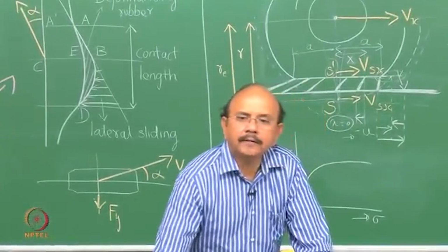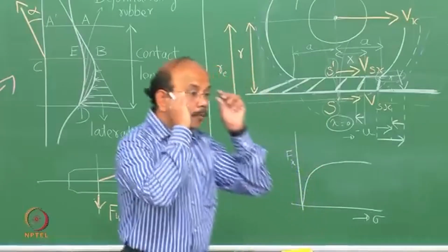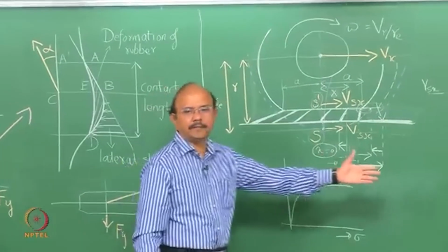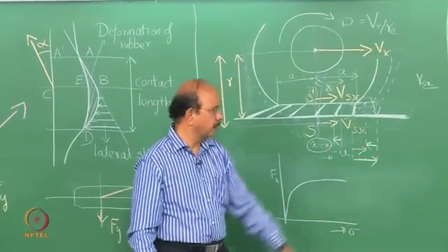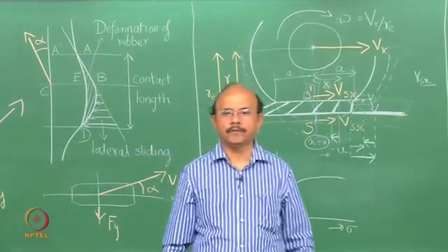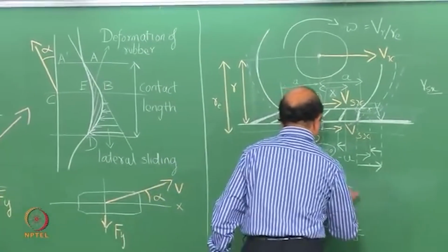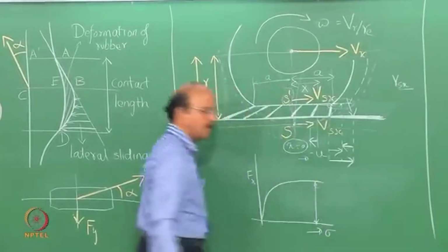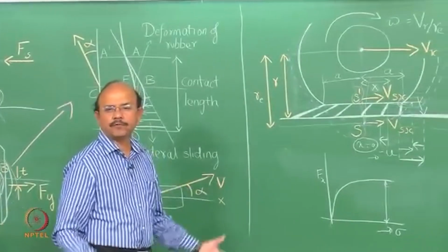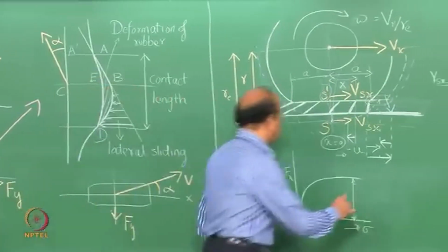One of the quantities of interest to us, you will see that later, is always the slope here, which can be approximated, if you look at kappa, to be 2cp a squared. And what's this quantity? That's the maximum force, and the maximum force would always be equal to mu into Fz. You need not even look at any of these things. So this would be mu into Fz.